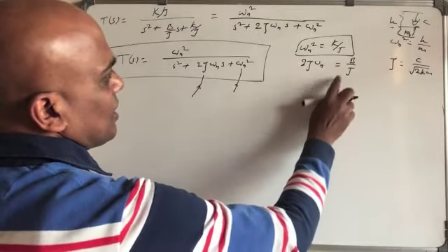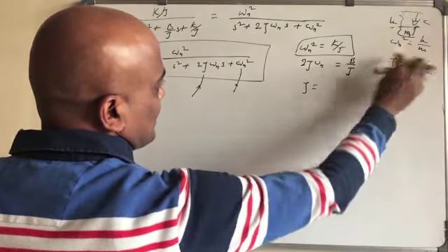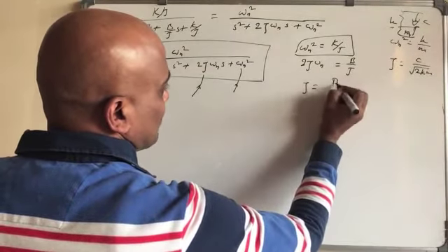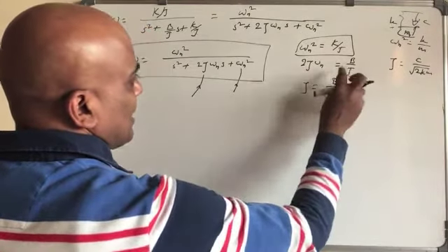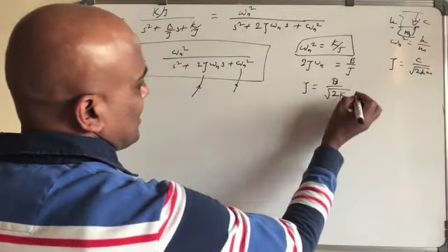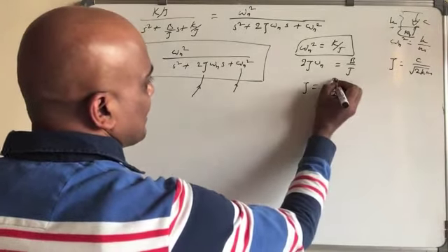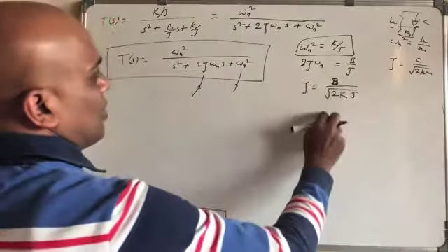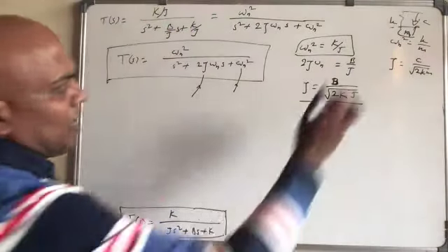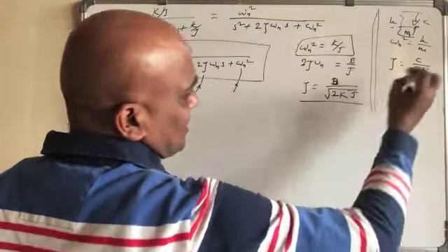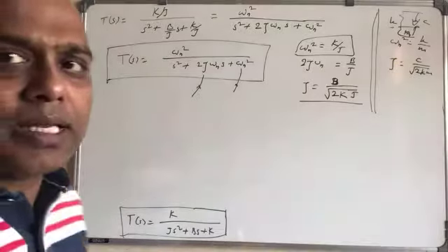So here your zeta is equal to, c and b are equivalent, so b over root 2, K is big K here, and J in place of m. So zeta in this case is b over root 2 kJ. So always, whatever you studied in a spring mass damper system, you can apply it here. The same meaning basically.